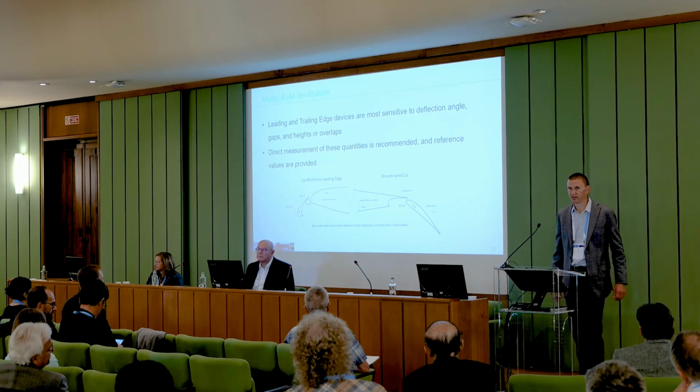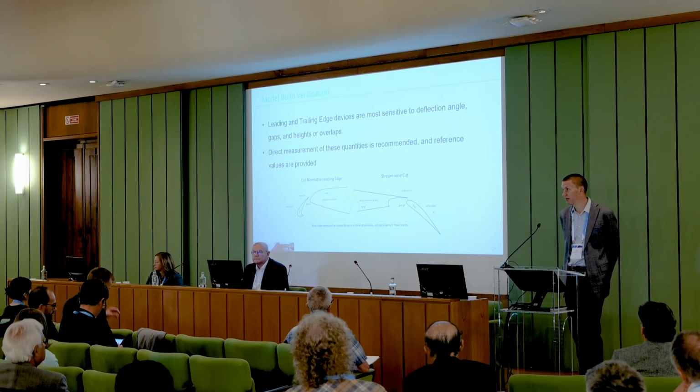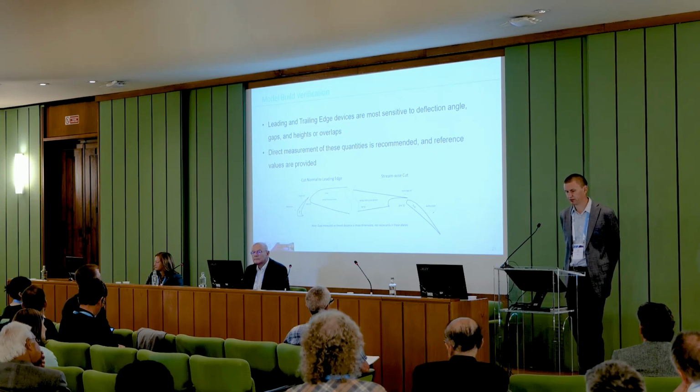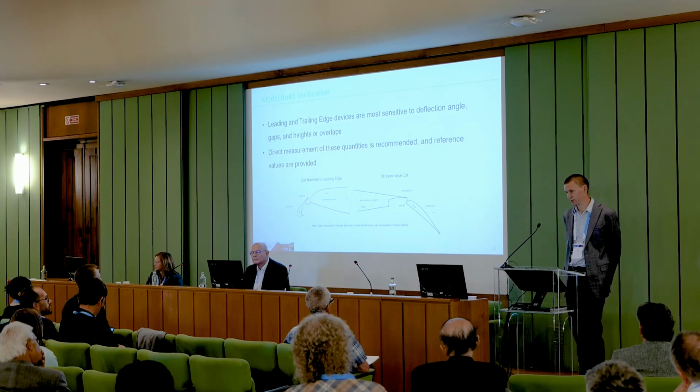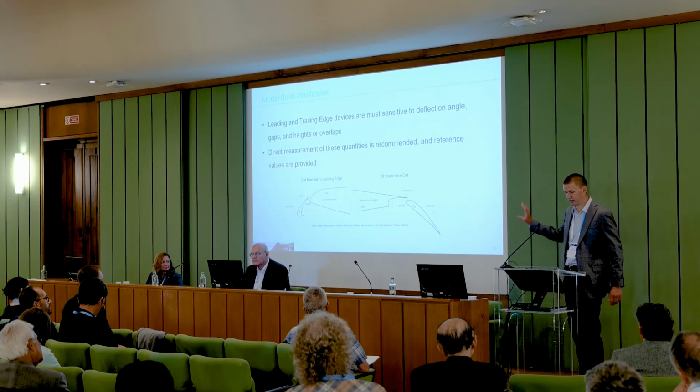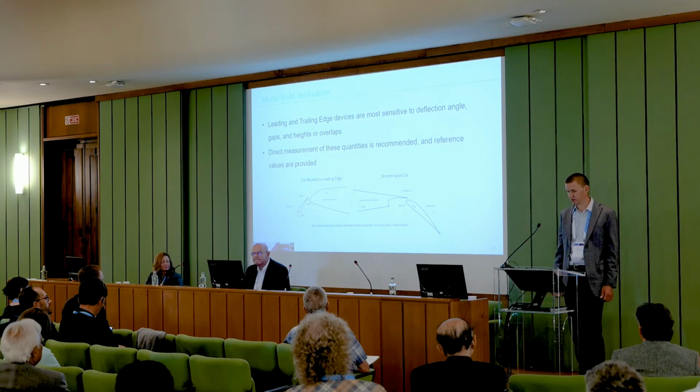That's not so apparent how to get that from a CMM. There have been people, Onera in particular, that was pretty clever about how they did their CMM inspection, and was actually able to derive this data. But this paper is essentially highlighting that we really want to directly measure these. So we provide locations where the direct measurements should take place, and methods to do so. Really highlighting that for everybody that builds a model, we want to have this data.